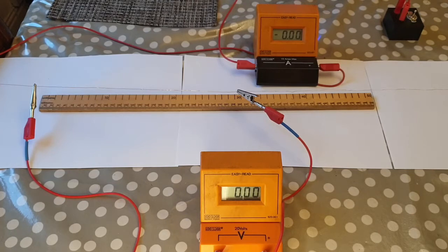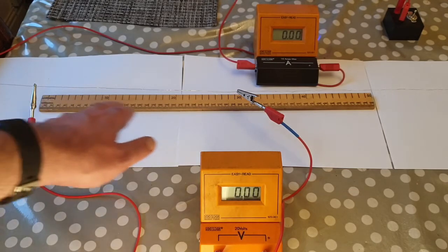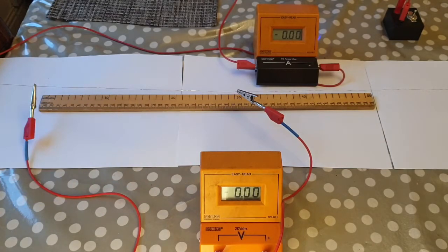So we've got two things so far. The resistance of a wire is directly proportional to its length, and the resistance of a wire is inversely proportional to its cross-section area. So what else have we got then? Well, the only other property of the wire that could affect the resistance is actually what the wire itself is made of. Now, this is copper.